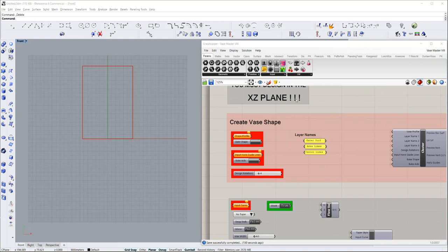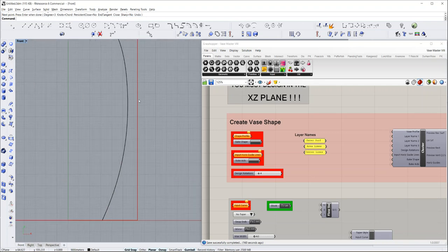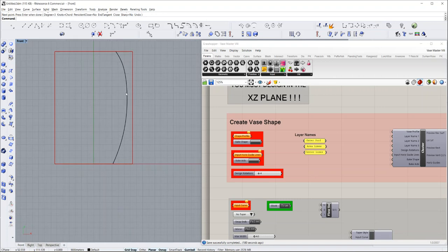So let's draw one. I'm going to use an interpolate curve. And I start at the bottom. Sometimes working from the top could cause issues. It's something I'm looking into. And I'm just creating a simple shape here. Now you notice I stayed away from the blank edge here pretty well. It's because we're going to be adding things that will start to fill in the surface. And we can move this over later on if we want to. So there's no point in forcing it right up against it now.